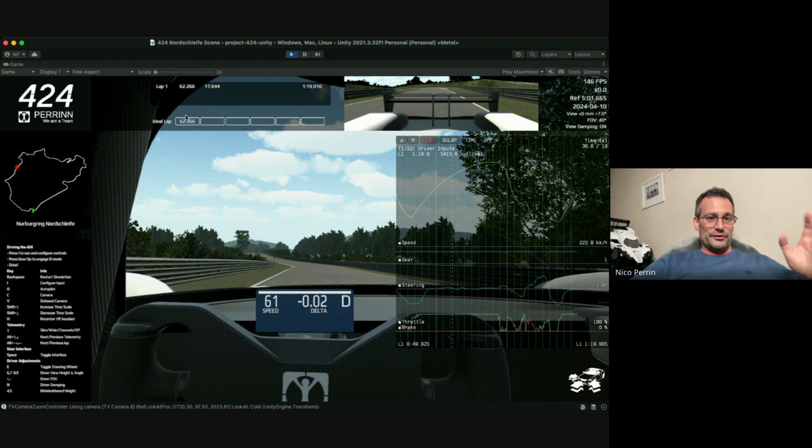So what we do with the sectors is we might drive 3 laps, which takes 15 minutes. We take all of the best sectors and we create this ideal lap. And that's the lap that will be compared to another ideal lap when we have changed the setup. That's a way to get really repeatable testing and more accurate results.